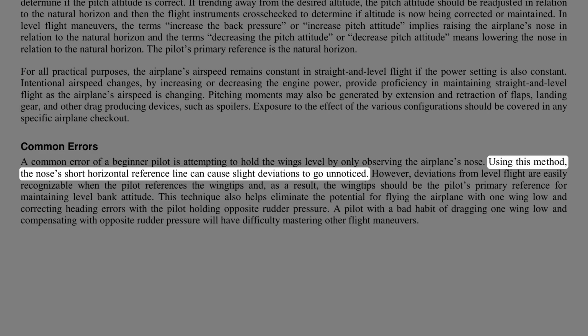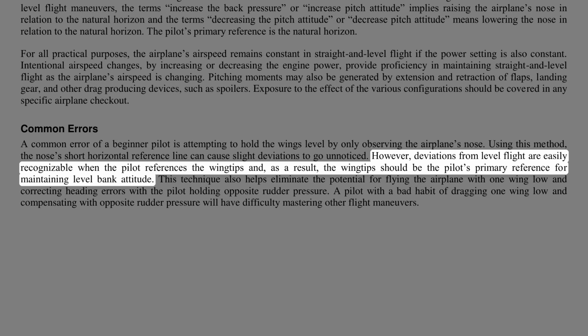Using this method, the nose's short horizontal reference line can cause slight deviations to go unnoticed. However, deviations from level flight are easily recognizable when the pilot references the wingtips, and, as a result, the wingtips should be the pilot's primary reference for maintaining level bank attitude.